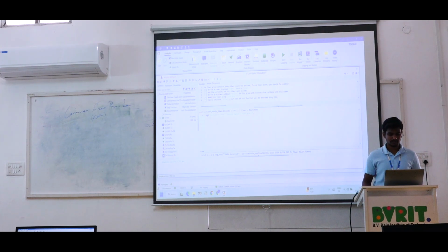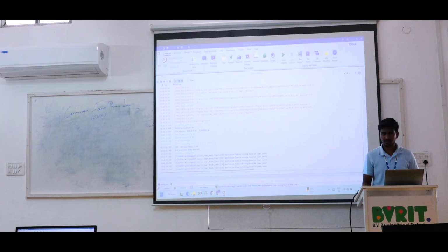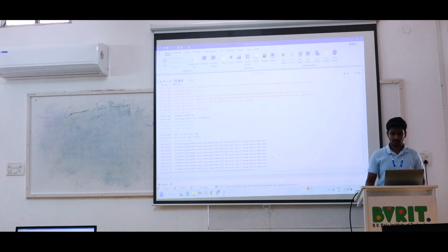So what statement do we write in the log? It is going to execute for 1 second only. So this is our concept. Now we write in our CAPL. Okay. We just run the script. Parallelly open the message. So our statement is running once every 1 second. We can see the output in our message, or in the top left we have a small message icon.